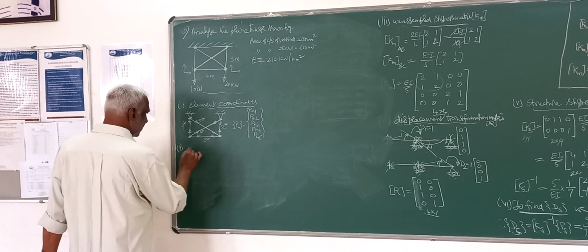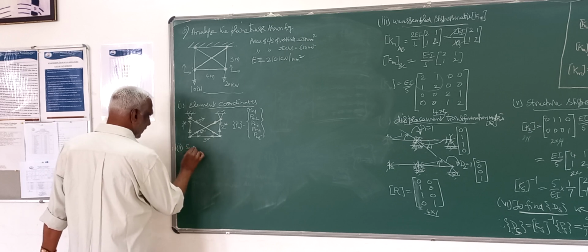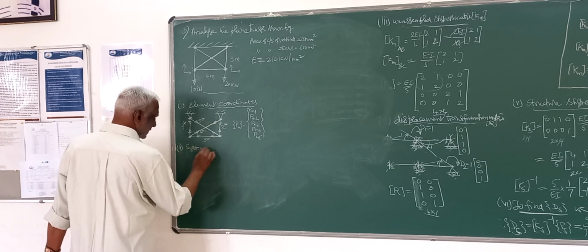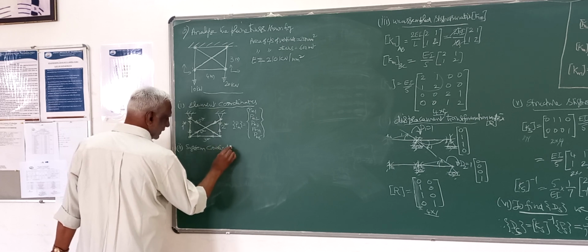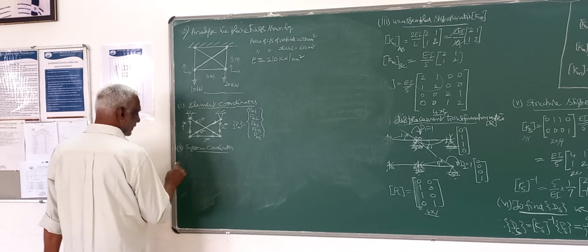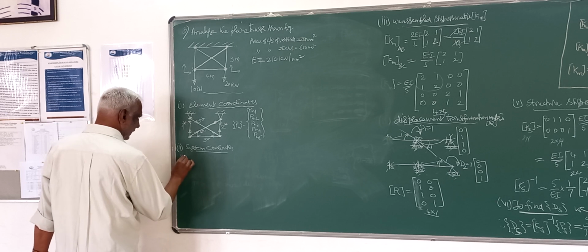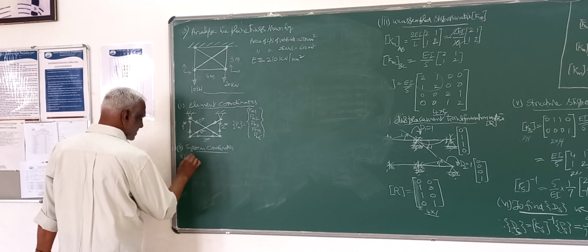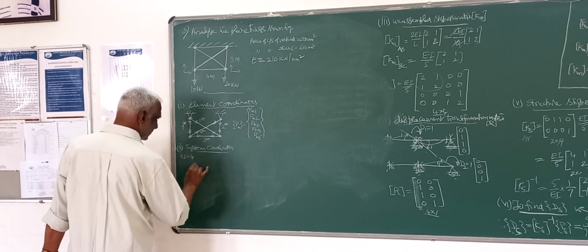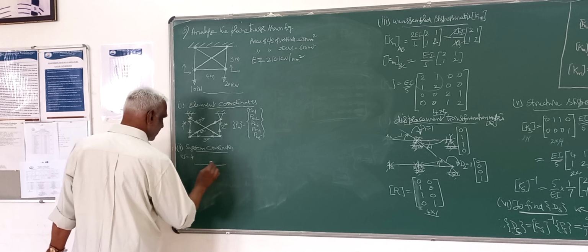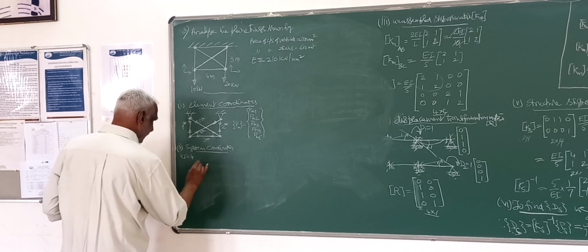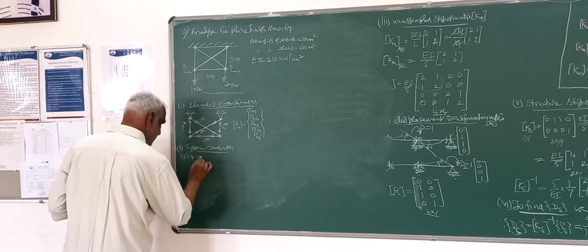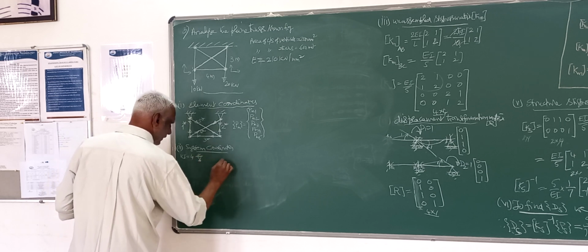Then second step, the system coordinates, let's say system or global coordinates. And that I have indicated. Here, the kinematic indeterminacy is 4. Already I told that 4 displacements we have to determine, which you indicate by this sketch of coordinates.